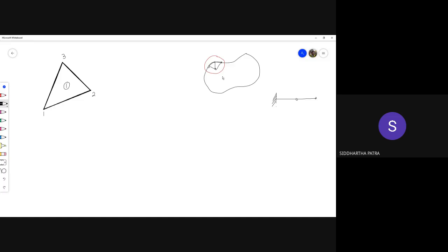So with 2D or 3D problems, the accumulation of error starts from the modeling of the geometry itself. So you can see the boundary is curved, but you are trying to model it with a straight edge, and obviously you are getting a different geometry.